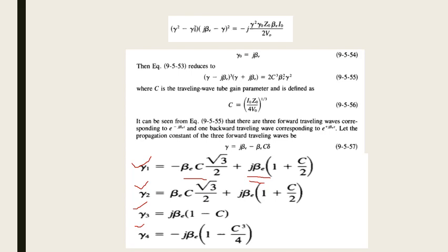Secondly, you are saying minus alpha. Minus alpha means negative of alpha. Well, attenuation is not there. Attenuation is not there, signal is growing. So when the signal is growing in the positive direction, what do you call this? Amplification. So whenever your gamma is working in gamma 1 mode, it is amplification mode. Means TWTA, traveling wave tube amplifier, works in gamma 1 mode.